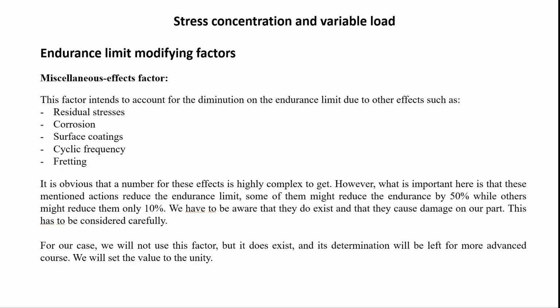Manufacturing processes include certain stress relieving practices, but you cannot be sure that all internal stresses due to the high amount of energy applied to the part at the beginning are going to go out. So there are going to be remains of spots of high stresses inside the part, and you don't know where, how many of them there are, or what region of the whole part is contained with residual stresses.